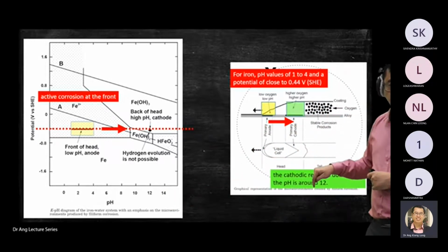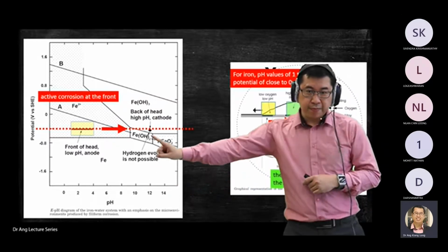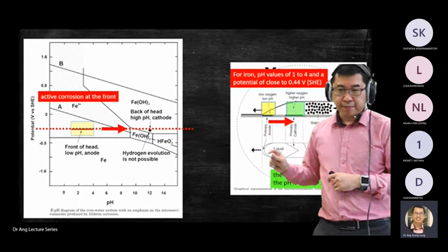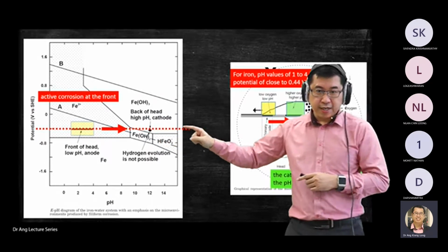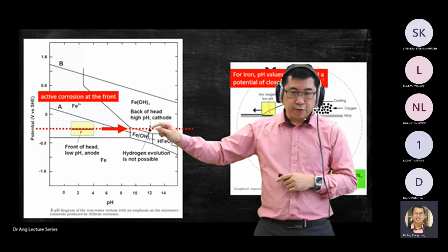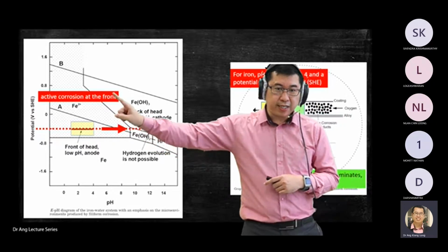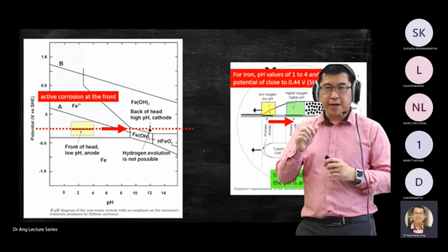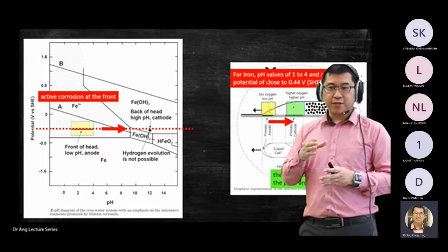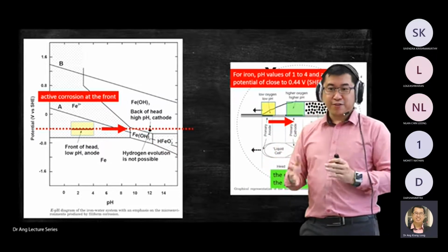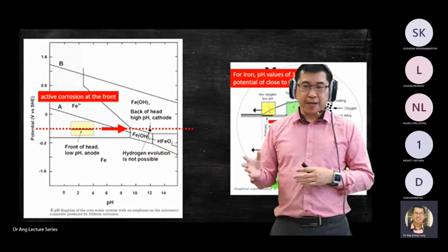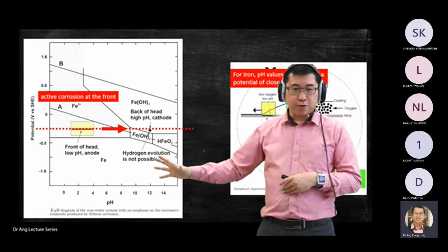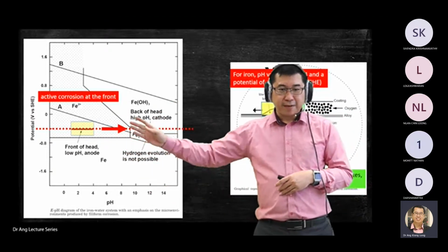Of course, in the test and exam, we will change this value. So at 12, you go up, intersect with this dash line, and you get one spot there. This is the spot where this happens. Once you find this spot, you have to identify what environment you have. On this environment, you see that there is a region. You studied the material module before, when you studied the metal phase diagram, you do the same thing. Metal changes from alpha, beta, and gamma phase if you change the temperature and so on. This will be the same concept, but now it's more on the pH diagram.